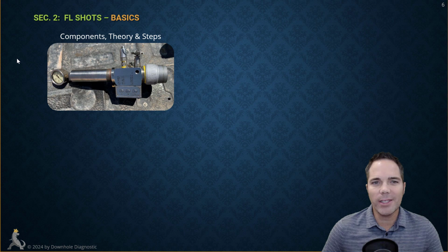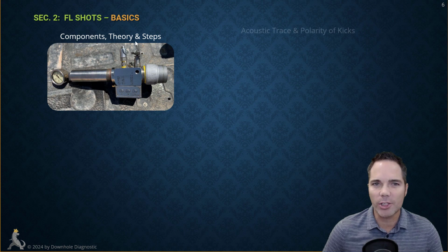We're going to start off by looking at the components of a fluid level gun. We'll look at the theory on how you take a fluid level shot and what's happening, and I'll show you the steps to safely connect and take a fluid level shot on a well.